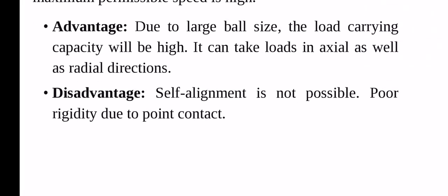Due to large ball size, the load carrying capacity will be high. It can take load in axial as well as radial direction. Disadvantage: self alignment is not possible for rigidity due to point contact.